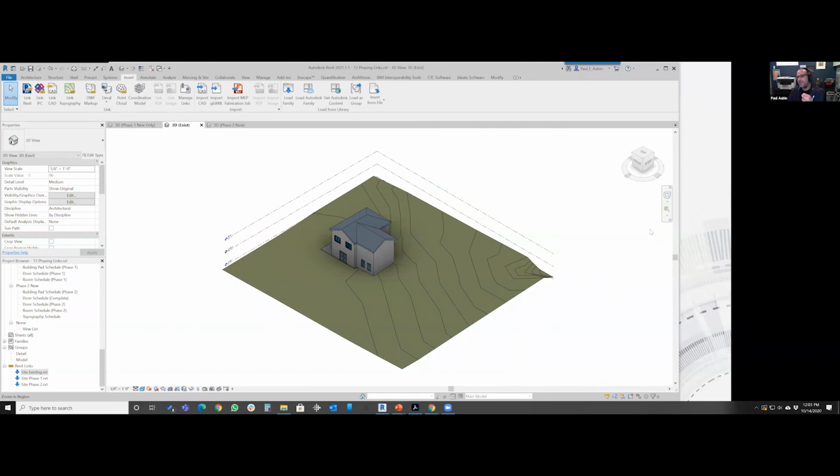So generally the two ways to do it is to co-opt the new phase filter or to use design options. Okay, the linked architecture file has phasing 2. Do I mimic all the phases? So you don't, as I think I just showed, hopefully you can see that on the first phase and the last phase, you don't necessarily have to mimic all of them. But if you find that confusing, it's not going to hurt anything if you do.